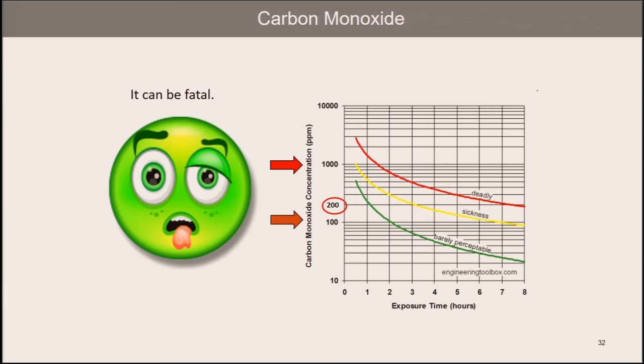First, understand that we in the industry strive by design to limit CO formation, or carbon monoxide, in our package boilers and burners to close to zero and never above 50 parts per million. Now, looking at the chart on the screen, you see exposure time in hours across the bottom horizontal and carbon monoxide parts per million on the vertical to the left. Note now the red arrows marking 100 parts per million of CO and 1,000 parts per million. And then follow those horizontal lines across to the right, lining up with the exposure times.